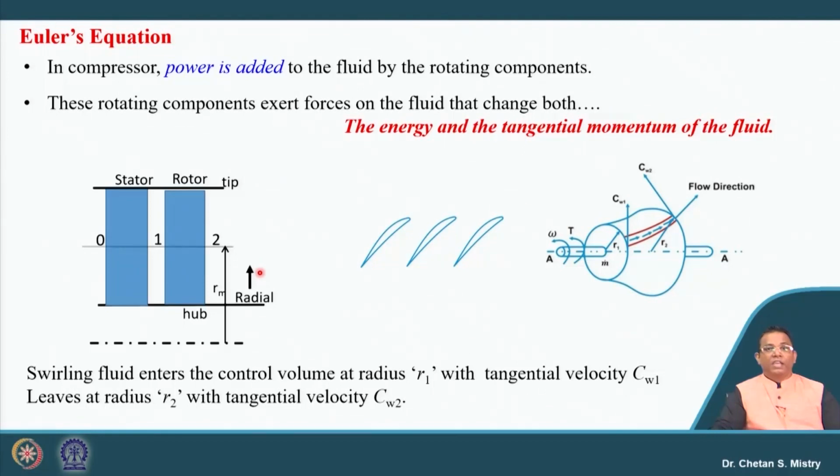So, let us say I put my cut section here, and if I look at my aerofoils, they will look like this. They are my stator blades, and in this direction I have my flow entering, the axial direction, and this represents my tangential direction. Here is my rotor, and as we have discussed, it rotates from the suction side to the pressure side, because we want to do work on our working fluid.